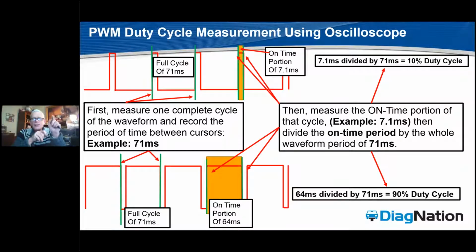What does that mean? Instead of disconnecting each wire and measuring between here and here with a simple voltmeter to say, does it have 5 volts, yes or no? We're taking that circuit apart in a lot of ways when we're following that DTC chart. Using this method to look at pulse width modulated circuits, we back probe the load in the output device and possibly back probe the PCM on the same wire for the purpose of voltage dropping, and we turn that circuit on, and there's 15 pages of diagnostic answers right on one screen. Guys, this is huge, okay?